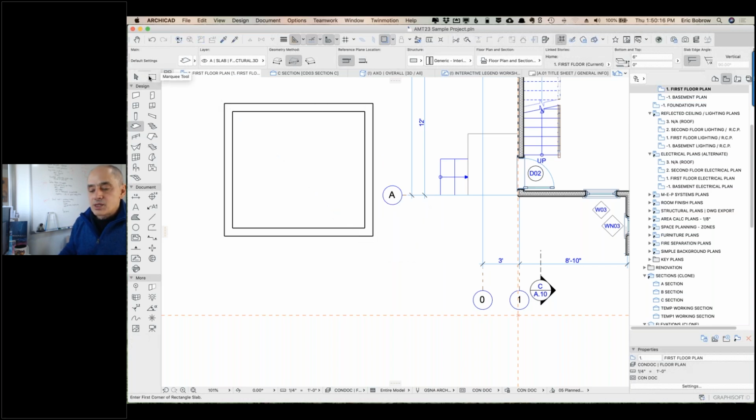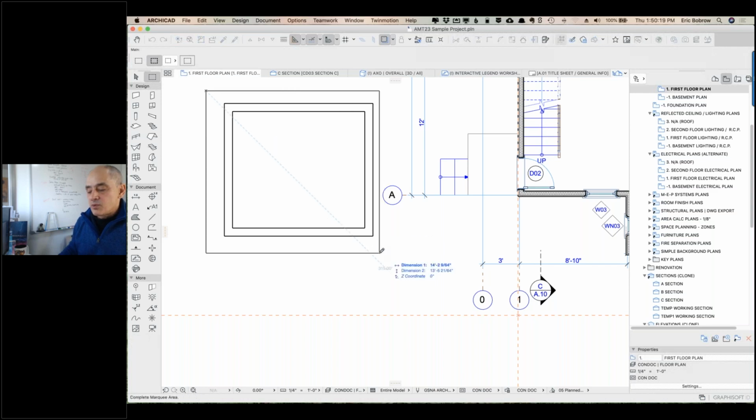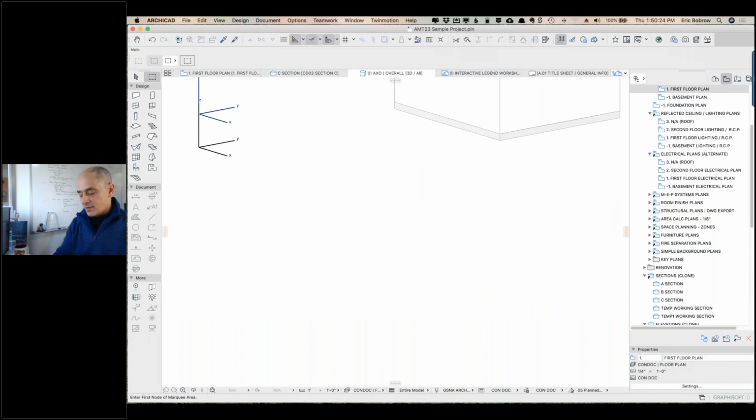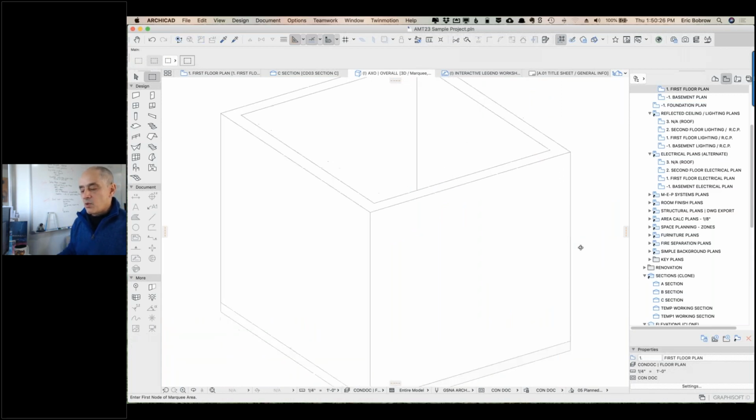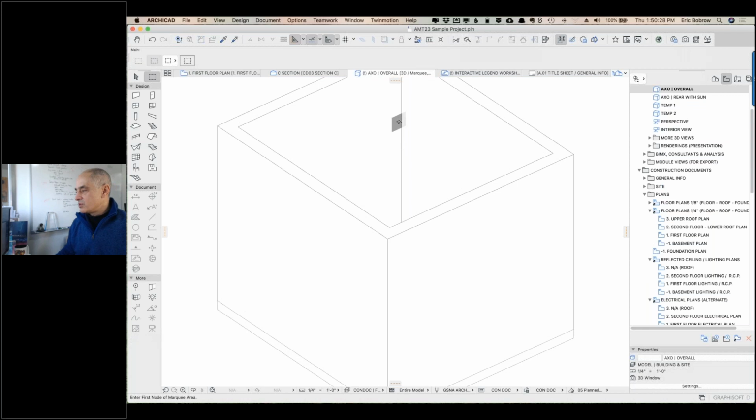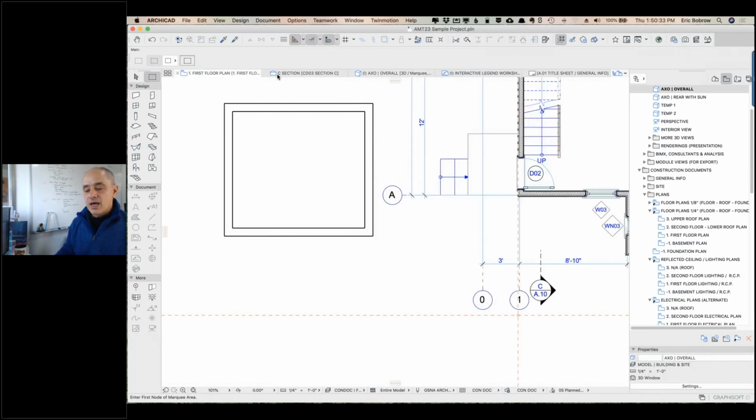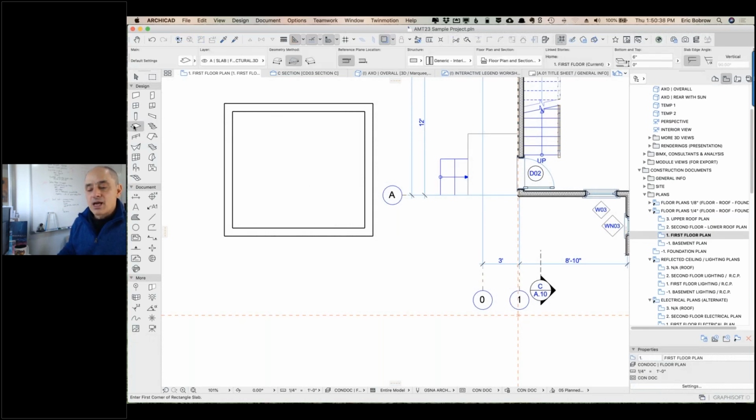And now let's just take a look at this in 3D. Now, of course, this is very boring. It's just going to be a rectangle. Now what if we wanted to put in a 2x2 ceiling? Now I'll go back to the floor plan. And so first thing I'm going to do is say we could draw in a ceiling as just simply a slab, and then get line work for that ceiling that represents the 2x2 pieces. So that is one approach. How would we do that?